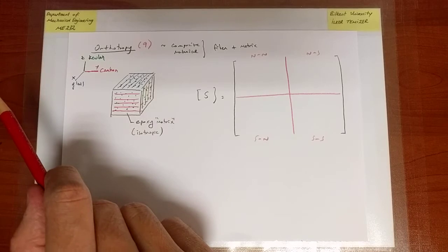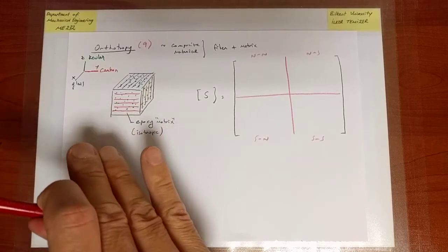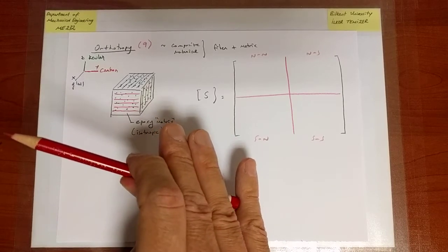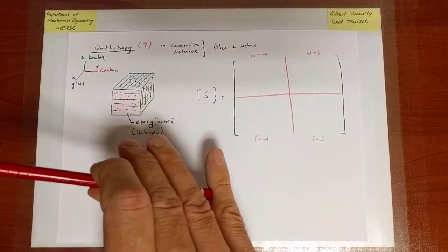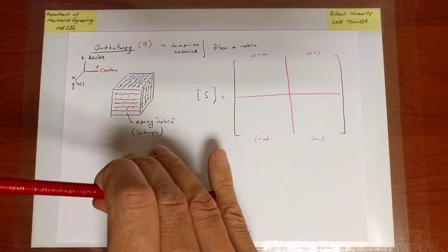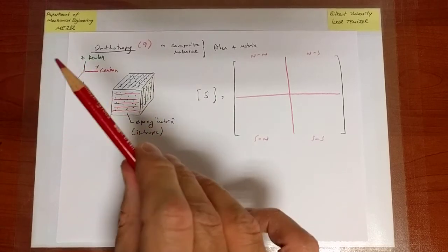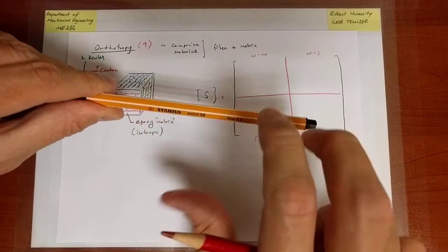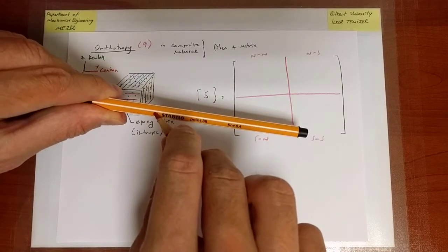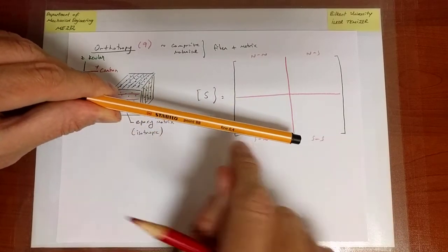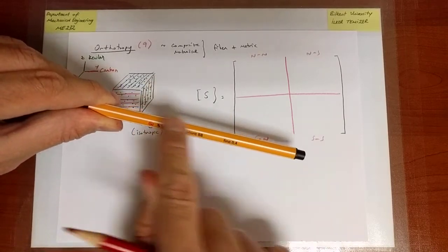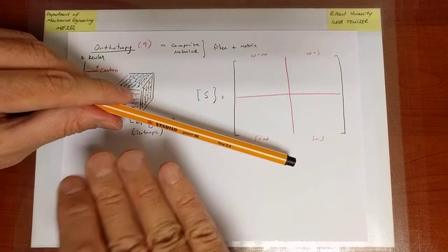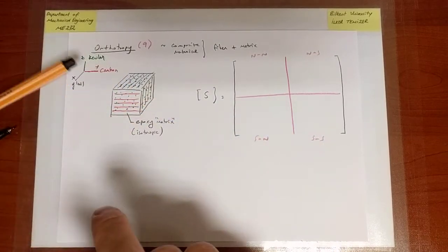So we're going to see in our next topic that for a given state of stress, if you choose different coordinate systems, the same state of stress will have components that appear differently. The values of normal and shear stresses will seem to change. And that change is occurring because although you're describing a certain state of stress, let's say you have a beam and you are bending it, and at that point there's a certain state of stress and you're interested in writing it with respect to a coordinate system which may or may not align with the axis of this beam. So different choices will lead to different expressions for the stress components.